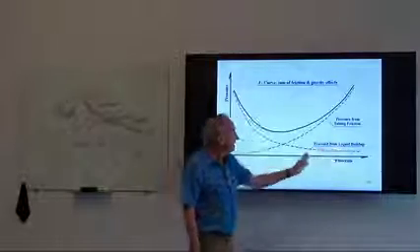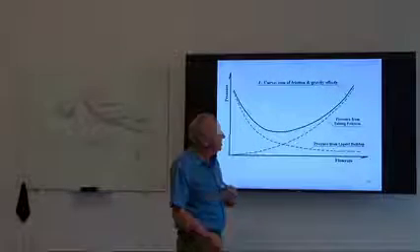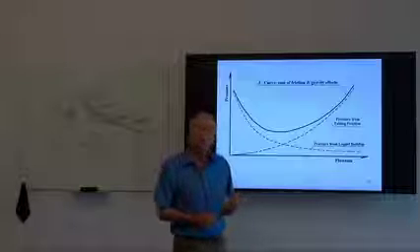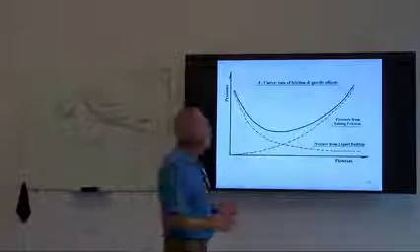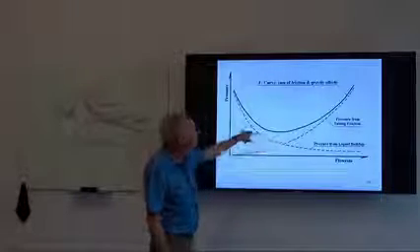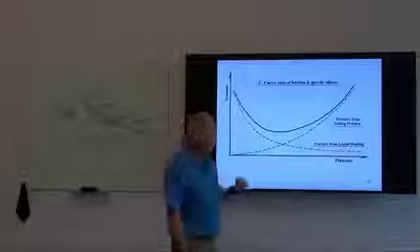As the flow rate drops off, the mixing ability gets worse and worse. The accumulation of liquid on the tubing wall becomes more prominent. Flow reversal starts to occur, and we start to see bottom hole pressure building as a result of accumulated liquid.